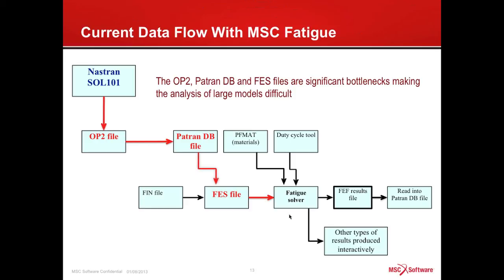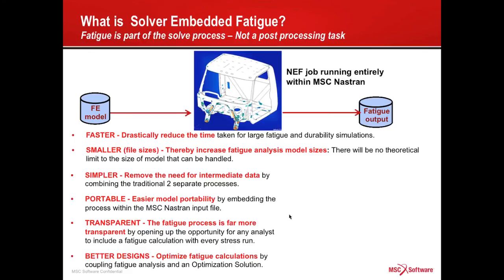So the concept of solver embedded fatigue is to recognize the fact that those stresses aren't actually needed. Take the fatigue solver and embed it directly inside the stress solver in order to be able to do fatigue calculations simultaneously with the stress calculation. So that is basically the concept of solver or Nastran embedded fatigue.